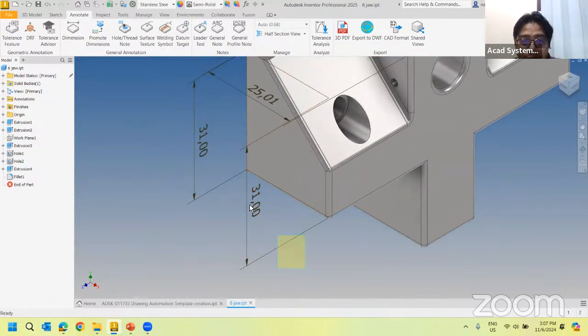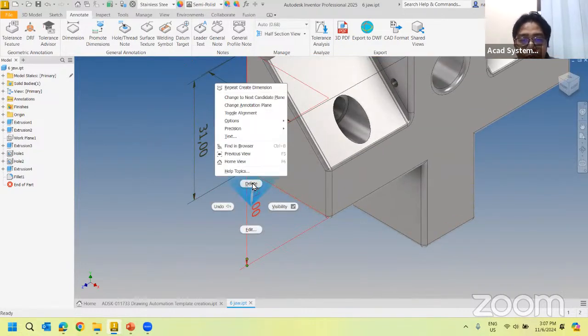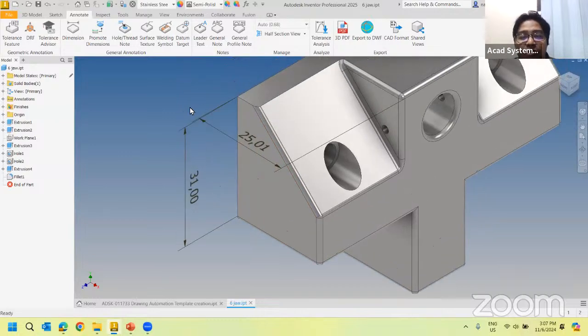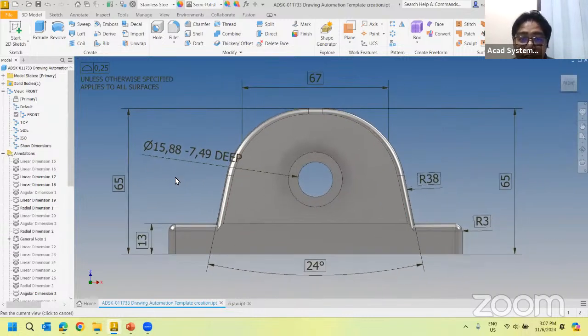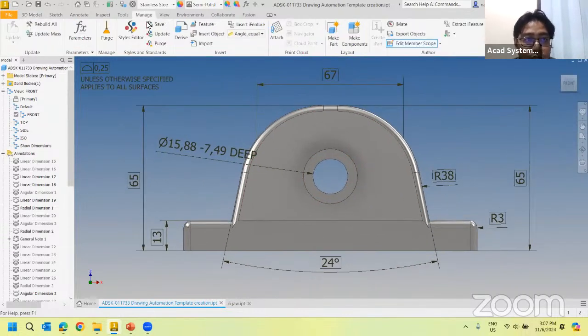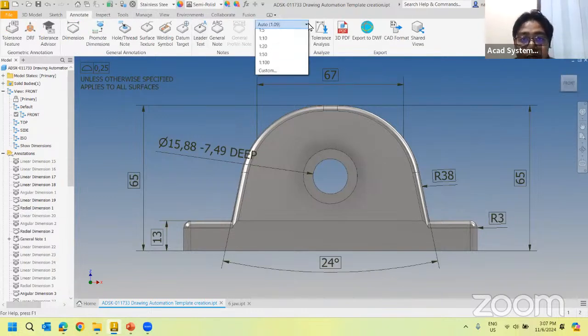Now, let's say I have my annotations, and I would like to change the size itself. Right? So one of the methods is that you can change the scale factor. You can go to Manage, and they should have the Scale here. For my case here, it does not appear to allow me to change. But if I use a different example from here, under this file, I should be able to change the size from here.